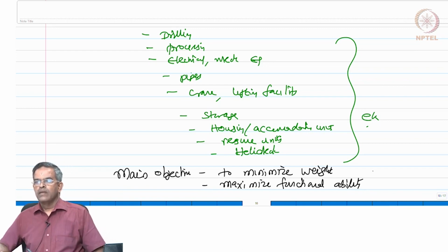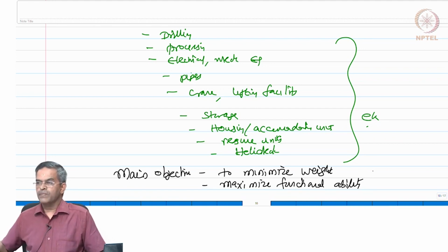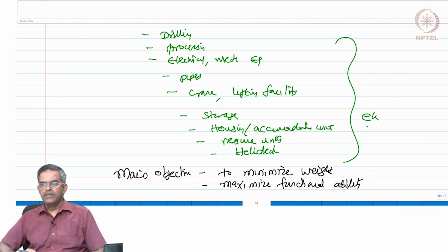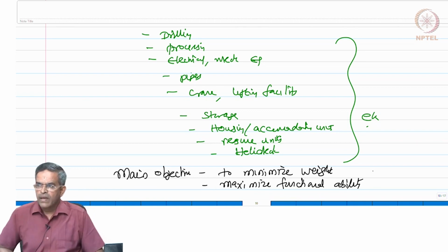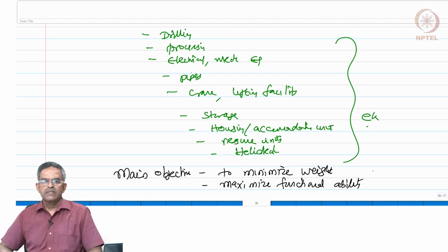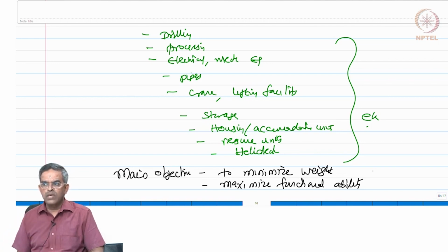Okay. Therefore, friends, the functional design of a topside or any strategic structure preludes the structural design. So, ideal design philosophy maintains the equilibrium between the applied load and resistance that can be offered by the structural system. Unlike in conventional design practices, where resistance is accounted only from the strength of the material, for strategic structures or form dominant designs, the resistance is also offered equally from the geometric form.